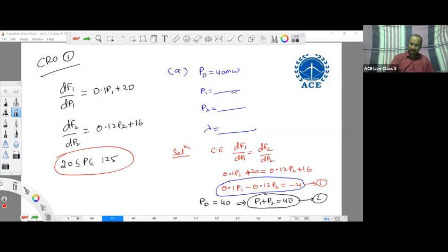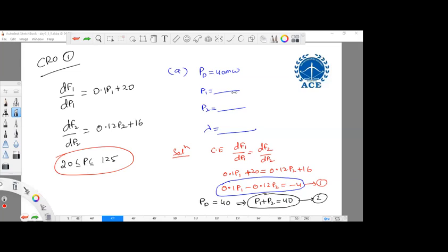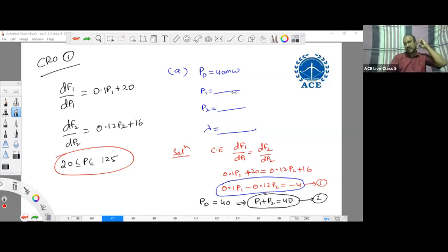Okay. So we are using Buchholz relay only for interturn faults, sir. Yes, for interturn faults, Buchholz relay is used. Even when short circuit fault takes place, if a differential relay fails to operate, then it will act as a backup for that. Okay, sir.